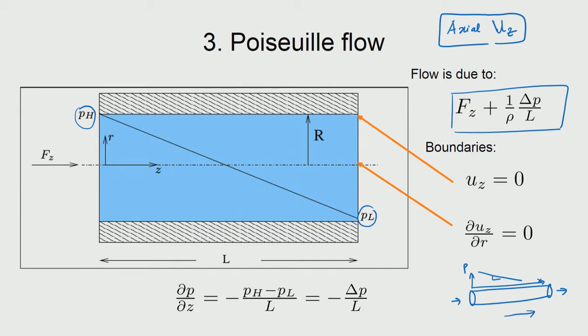Now, the inner walls of the tube are assumed to be rigid, smooth and so on, and so the boundary conditions that are applicable are that the velocity at the inner wall is 0. This is from the no slip condition, and we also want to say that along the diameter there is a symmetry, which would mean that the velocity profile should have a finite value at r equal to 0, or you have a slope that is 0. So, both would mean the same thing when we are solving the equation, but we need to use one of those two principles at the center, that is either the symmetry or the velocity being finite.